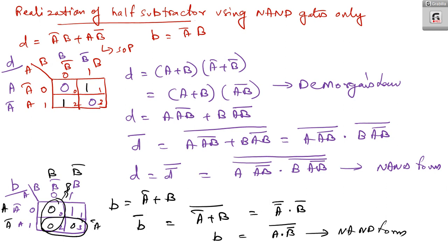Okay. So this is A dot B bar. A dot B bar whole bar. Now let me think of this borrow part only. Now if you are going with this term, see what happens. A is here, but here B is already there. But here you need to take B bar. But we have A B bar. So here what happens is that you will get an additional NAND gate.